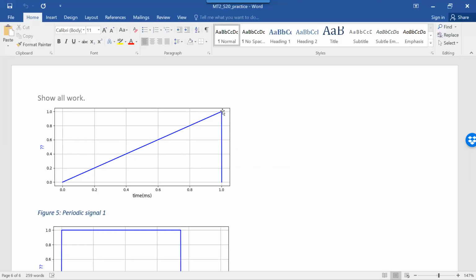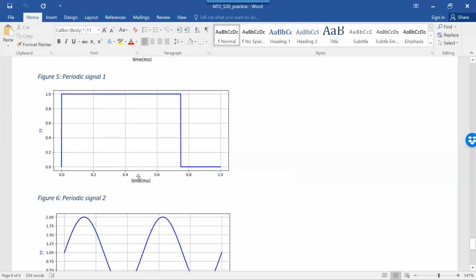And so what you get is a DC offset of 0.5. Here, you know that it's not at 0.5, you know that it's not at 0.8, but it goes to 1 and then comes off. So there's going to be some average between 0.6 and 0.8, closer to 0.8, where that'll be your DC offset.